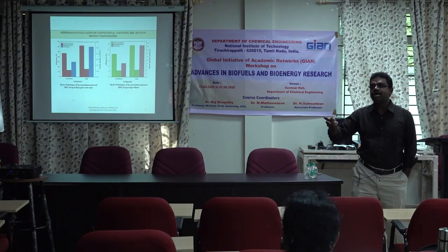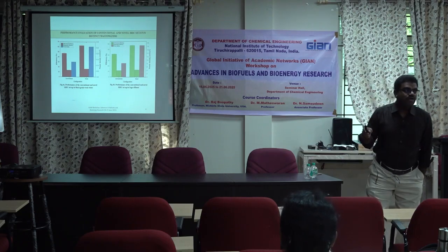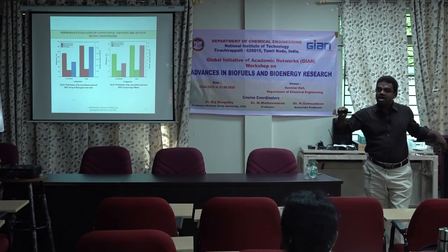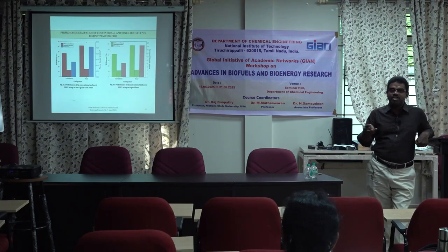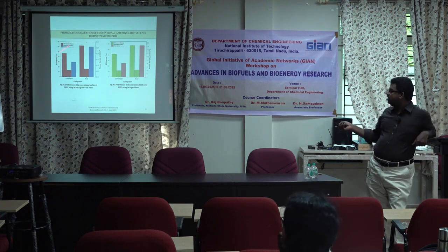To avoid that, and to check whether our system is purely giving better performance as compared to the conventional system, we killed all the microorganisms from both wastewaters and added new microorganisms to the systems. That is Shewanella species we added to the system. We tested the performance, and hence we got different kinds of performance here, which we can see.